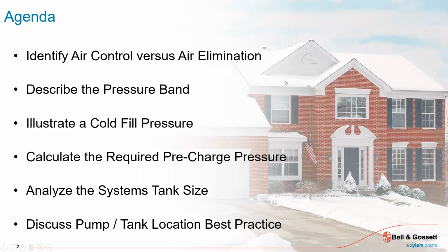as water is heated, there's expansion. So there's going to be a system pressure. So you're going to start cold. You're going to have operation where the water is heated and expands and increases in pressure. Then you're going to have the safety, or that maximum operating pressure, which is your relief valve, stuff that's going to protect the equipment. You don't want system pressures to go beyond X.